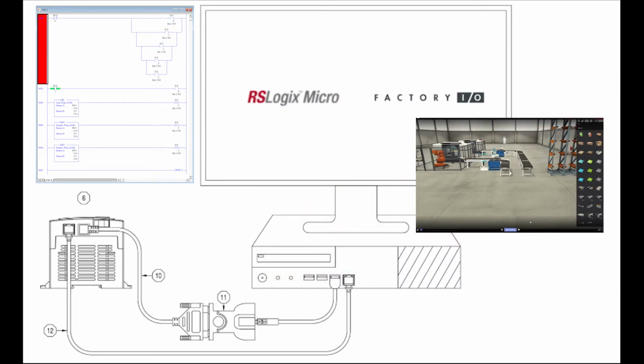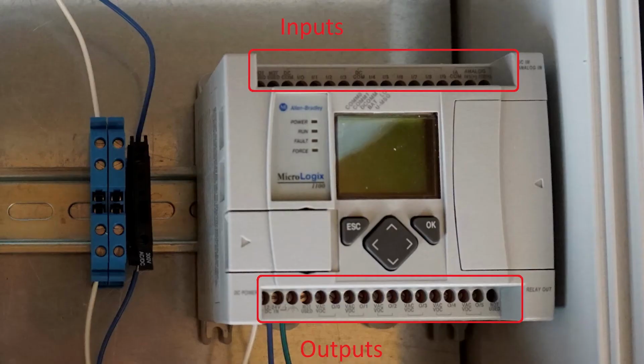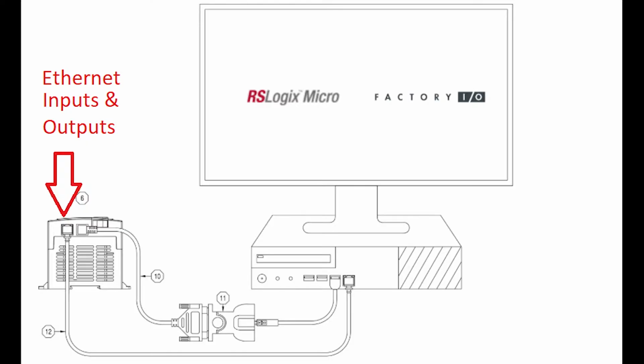A difference here between the industrial application and our simulation is that in an industrial application, the inputs and outputs would come from the PLC here, while in our simulation, the inputs and outputs would come from an Ethernet cable that connects here on the PLC. This Ethernet cable then connects to the computer running Factory I/O.